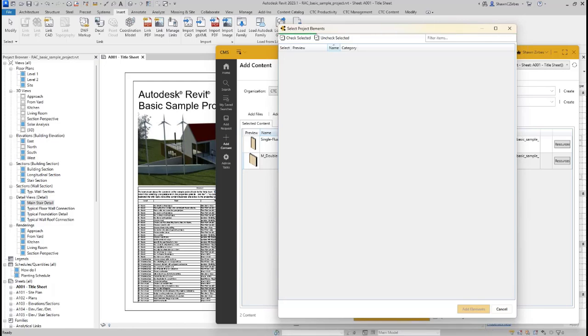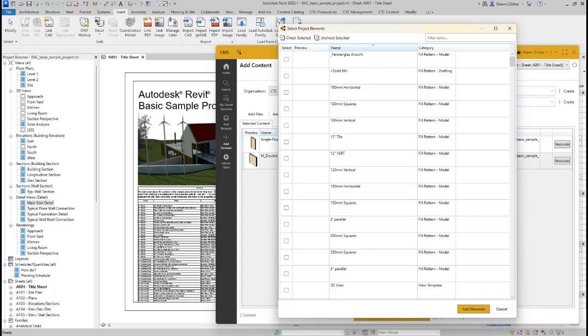And by the way, while this is popping up and processing this list, I want to make another little comment for you. If you're going to process onesie, twosie items like I've done today, no big deal. Click process, let it rip. Just watch it happen. It's kind of fun when you're just like, 1 to 10 items. If you're going to be processing thousands of items though, do it when you're not going to be using your computer, because it will continually activate the background session of Revit.